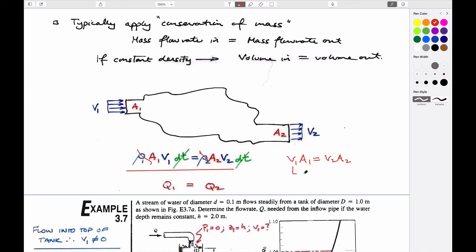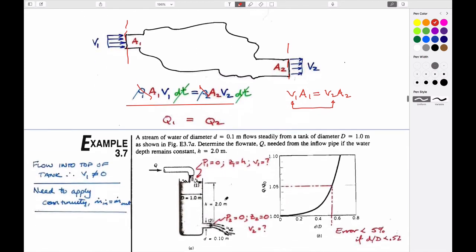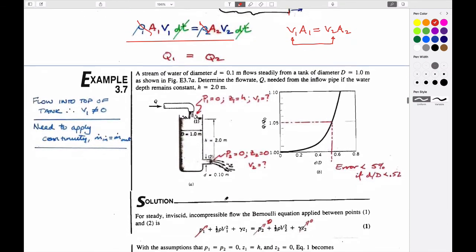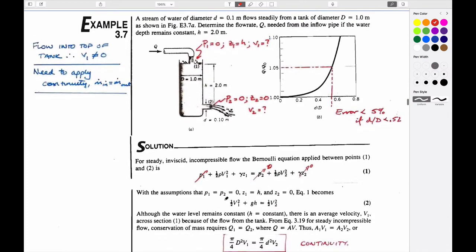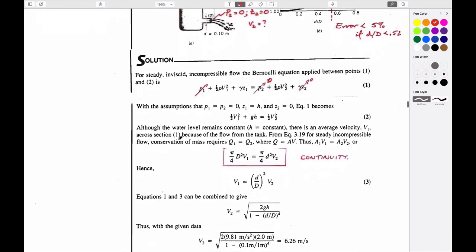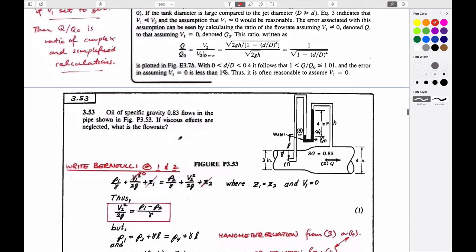And so we can relate the velocities at the inlet and outlet purely in terms of those by drawing a control volume that cuts it off at these particular locations. We can also look at unsteady problems by looking at flow rates out of a system and looking at how quickly this is replenished, for instance, and solve in time. You can go back to look at that if appropriate.